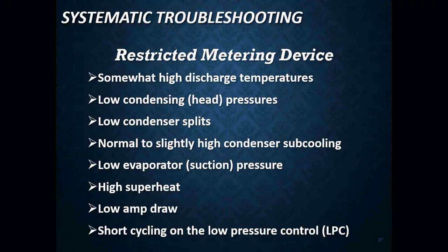Forgetting to purge your hoses when accessing a system. Remember, that's one of the guidelines that we should be doing, is purging our hoses of any air or non-condensables that are in our refrigerant gauges before we hook them up to a system.